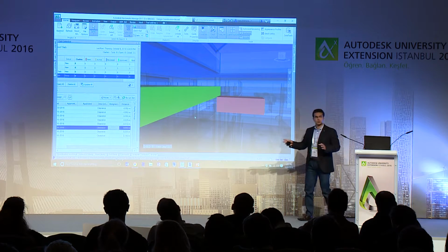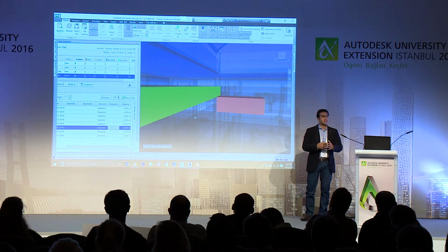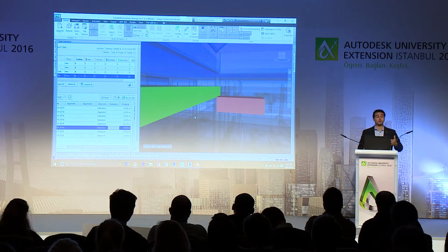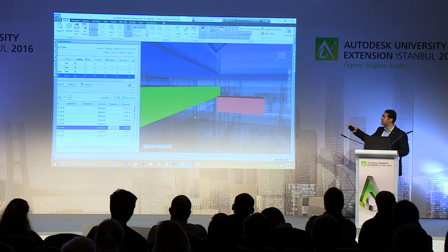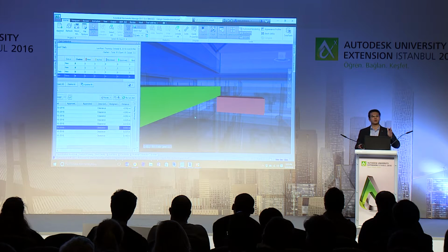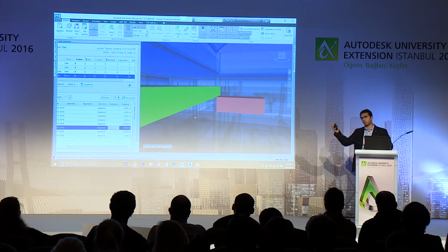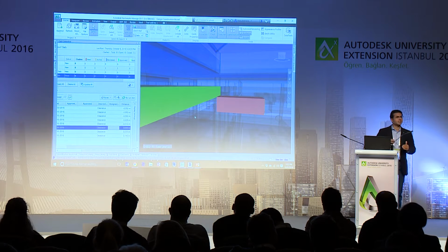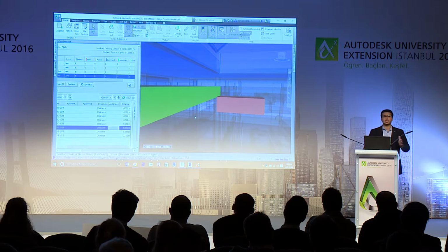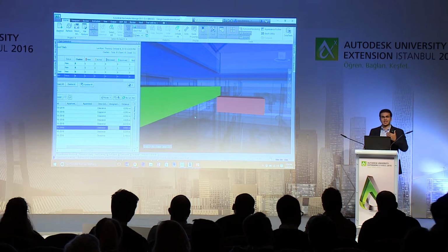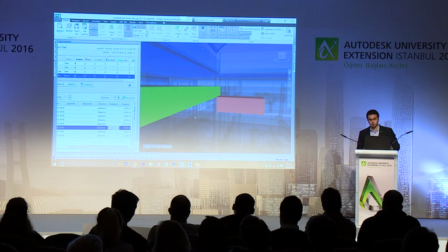One thing here very quickly is to know that the ability to group the clashes is actually more flexible, which means you can manually select and group clashes. Unlike Glue, where you have only 2 options, from one model to another or from the second model to the first one, here you can make groups by manually selecting certain clashes and grouping them for resolution. So you get more flexibility to resolve clashes of a real project.